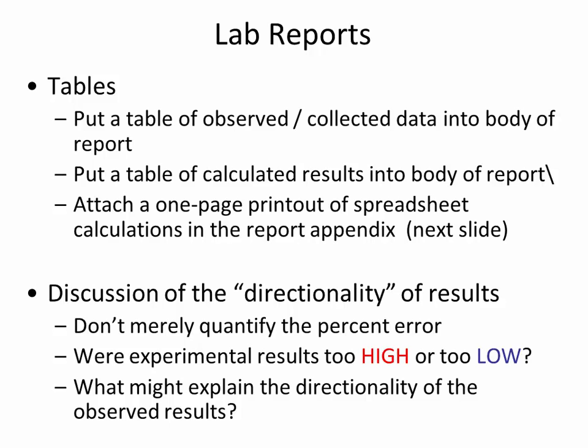And then the student had an experimental metacentric height of 0.007, so off by an order of magnitude. And the reason they said it might have been different is because the ruler you're using isn't very accurate. I mean, that's not plausible. For a result to be off by a factor of 10, the fact that you're using a ruler that can only measure to the nearest millimeter is not a plausible explanation. The truth of it was that that student had an error in their calculations.